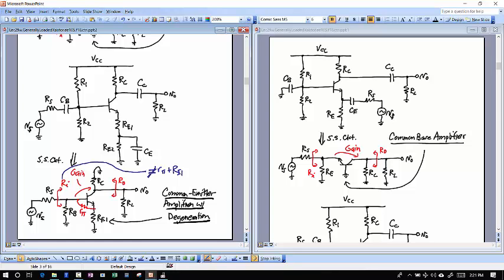That is not right. Okay, and so I'm going to even write there that it's not right. Put an X there and everything. Why am I putting so many things there? Because every time I teach a class like this, I see someone coming in saying the input resistance Ri looking into the base of this transistor is R pi plus RE1. Okay, that's absolutely wrong.